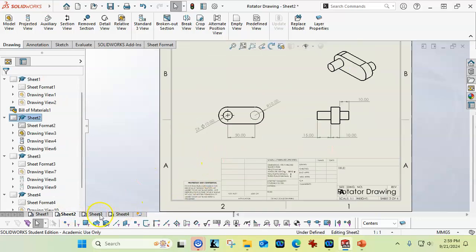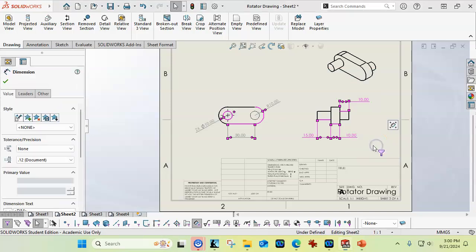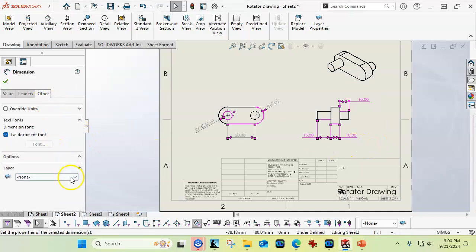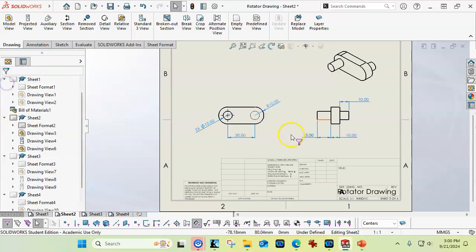All right, so in this case, I have the filters turned on. If you don't have filters, F5 shows and hides, and F6 toggles being active, but I haven't activated anything. So what I want to select for is dimensions, so that I grab all of the dimensions. And let's see, is it going to be under other? Yeah. So I can switch those two dimensions.